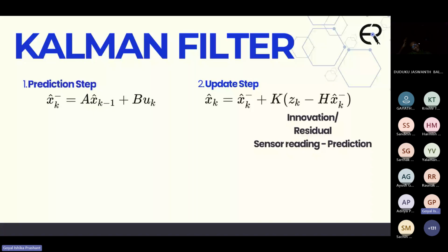So let's look at how a Kalman filter works. First, we have the prediction step. Now, x_k here with the bar on top represents the predicted current position, and x_(k-1) represents the previous position. But since it's without the bar, it means that it was the final estimate. And u_k represents the data that we got from our motor commands. So we add the previous estimate and these motor commands and scale them by some factors a and b, which are predetermined, to give us the predicted position.